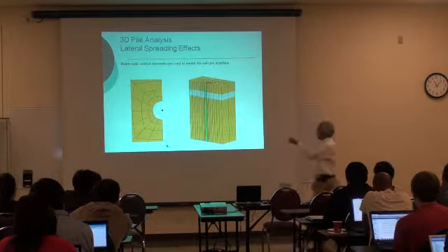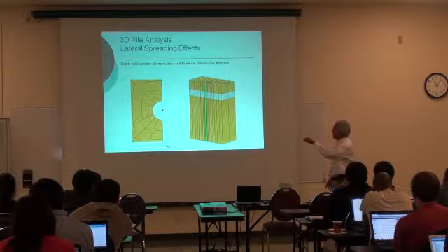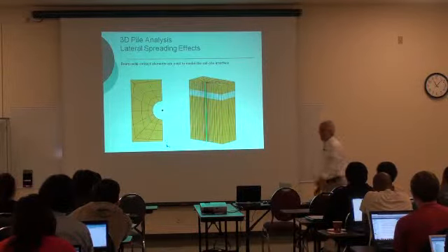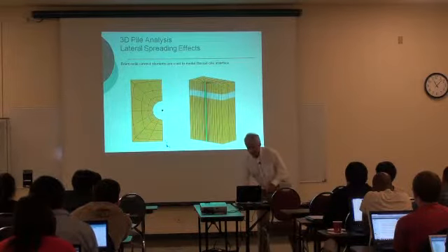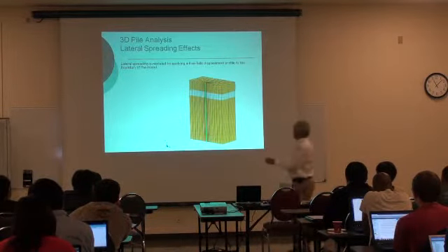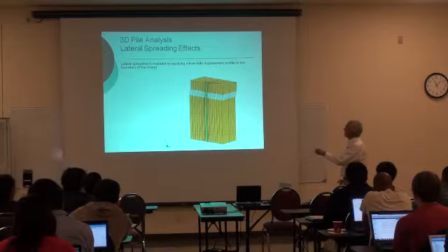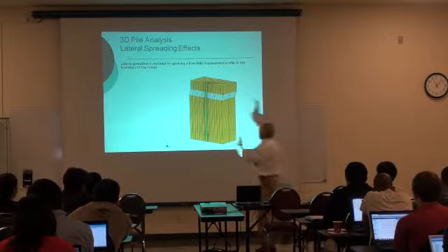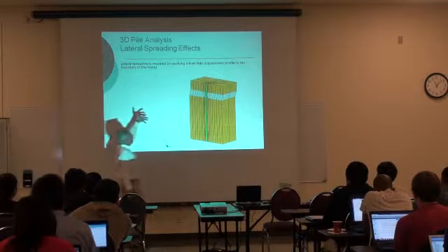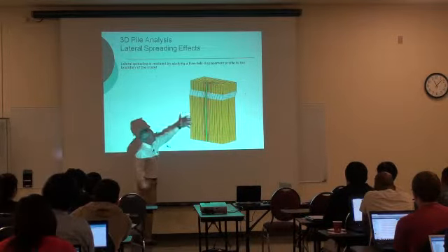This shows a plan view where you see the pile, and you see here the location of the interface elements. The boundary conditions that we apply are displacements here at the top and linear displacement on the boundaries in order to simulate what happens when the soil liquefies.